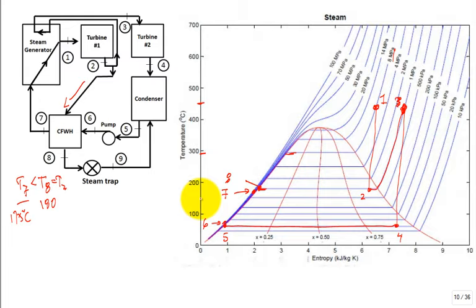Okay. Then we're going to put it through a trap. 8 will kick down and over to state 9, and 9 will also condense just like the condensate from 4. It condensed from 4 over. Okay. Now I have all of these states, do I not? 7, 8, 9, all of them on this diagram. True? Yes. 7 is compressed liquid. 8 is saturated liquid.